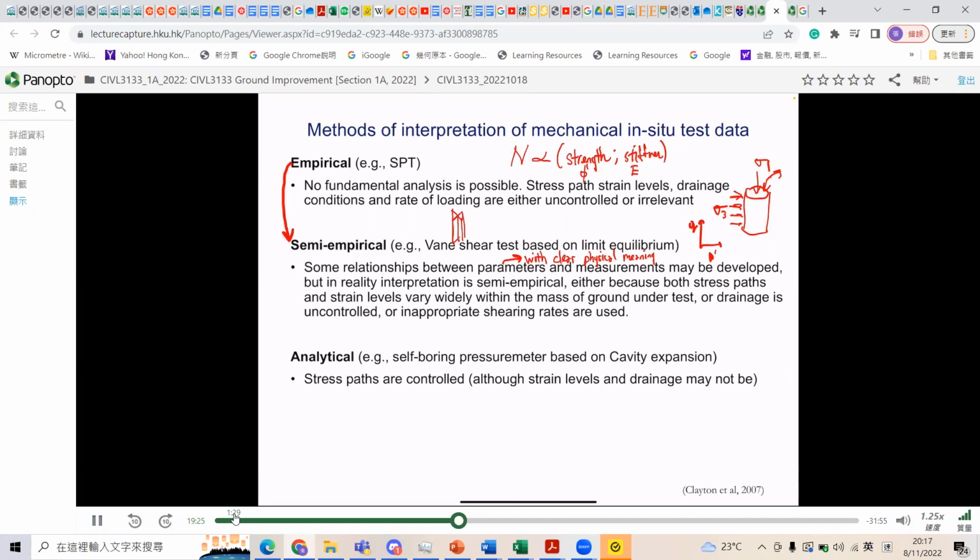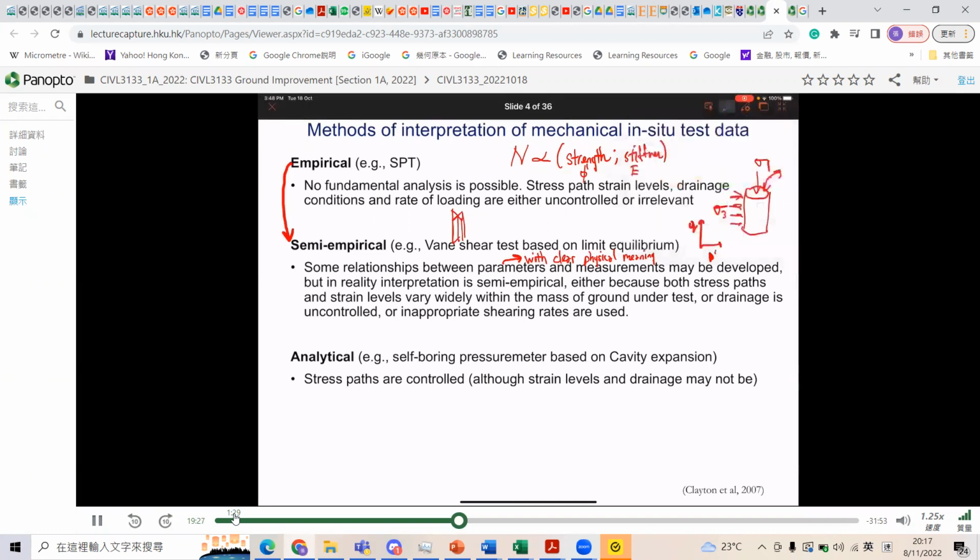Although it seems quite straightforward that, look, we assume that the soil fails as a perfect cylinder around this cruciform, the question we have to ask ourselves is, yes, but what assumptions have we made by assuming that this fails as a perfect cylinder?